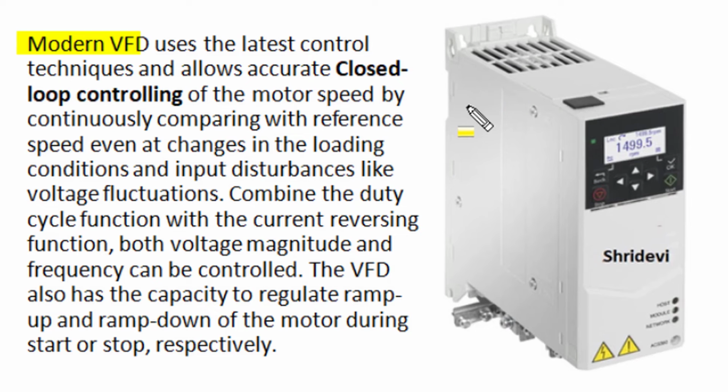Even when there is a change in mechanical loading of the motor or a change in input supply parameter, even in voltage fluctuations, the VFD microcontroller manages switching action in such a way that the desired operation of the motor at the required speed condition is maintained. The microcontroller unit combines the duty cycle function and control switching of IGBT switches with a current reversing function so as to manage the frequency of the output supply, and in this way we can manage both voltage magnitude and frequency as per our speed requirement.